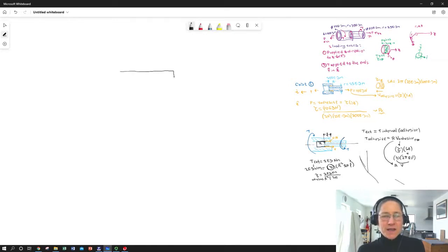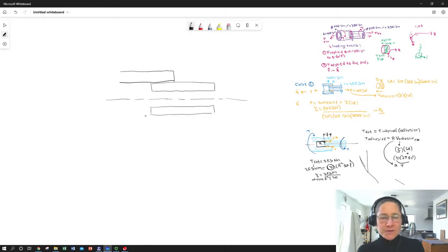So let's consider the same case, except this time somebody has said, okay, I don't have any glue, I'm going to pin them together. So here's our center line. This is again a longitudinal section through the concentric pipes. They're contacting, so I sectioned them right down through that center line parallel to the z-axis. So this is Z. So this is this section.